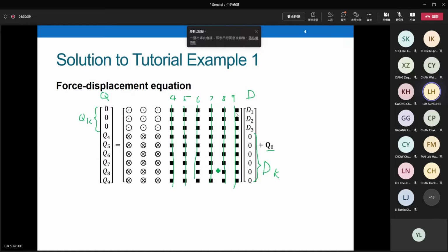So in step 1, you can immediately identify which part is useful in your matrix. When you construct your element matrix and do the matrix additions, you just need to pay great attention to row 1, row 2, row 3, and column 1, column 2, column 3, because they will really affect your calculations. For the remaining part, you may put them symbolically, call that K12, K22, something like that.